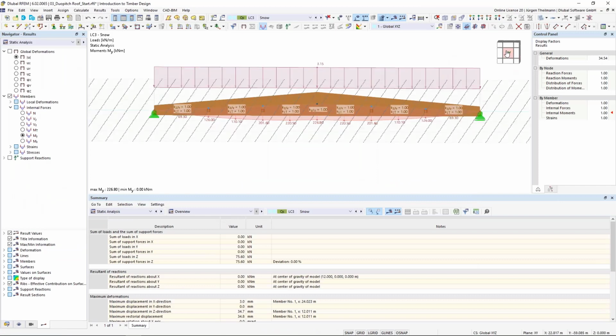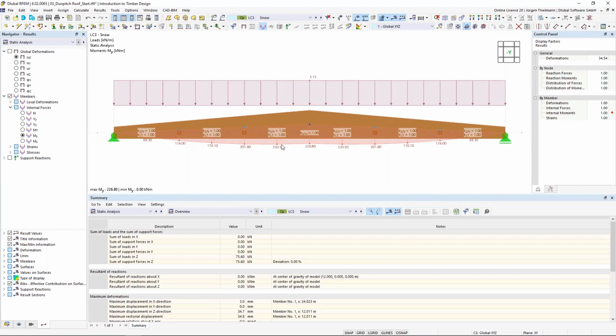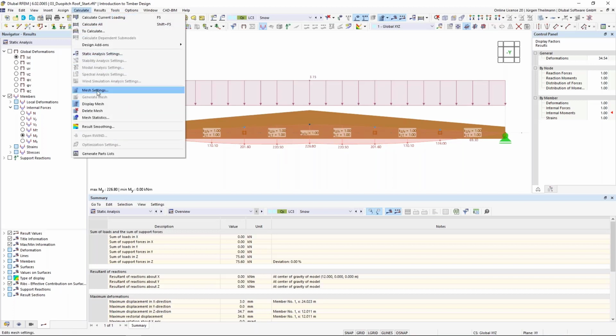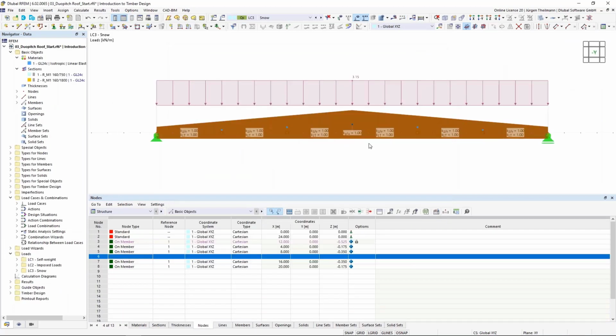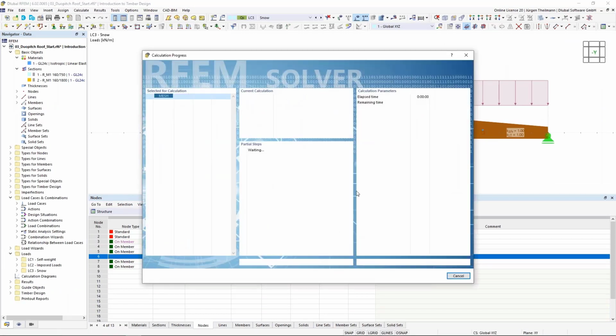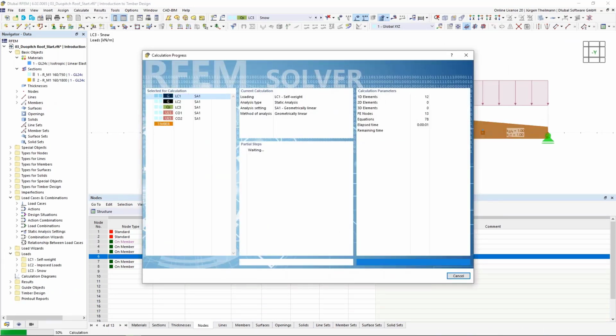And now you see this diagram for the bending. This is not usable anymore. So those of you who have already heard our training in the introduction to FEA know what comes next: the basic rule is to set every FE mesh, even on members, to be as coarse as possible, but still as fine as necessary. And this is a case where we need a finer mesh just to determine the place of the maximum bending stress in this member.